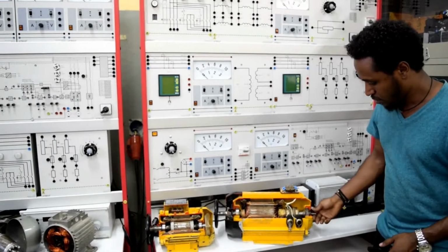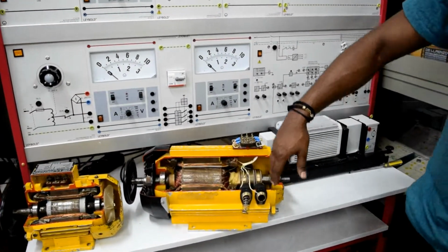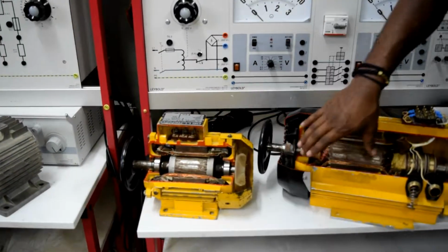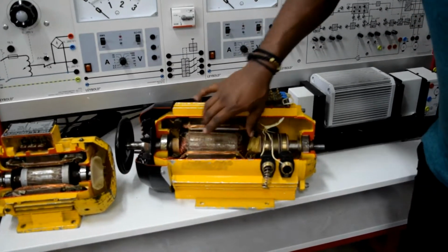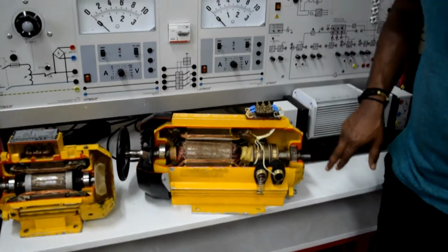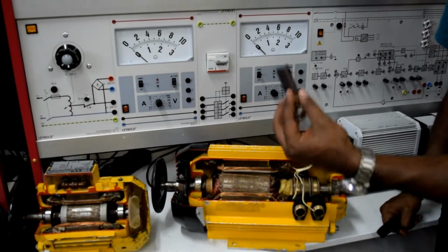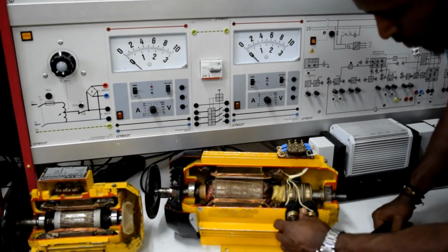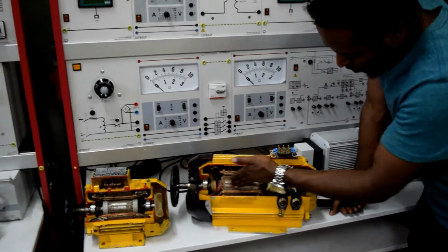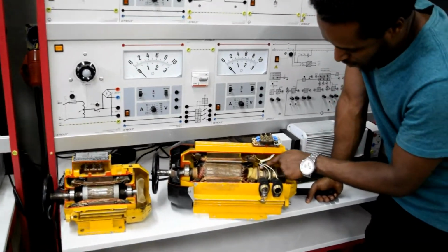So when we see the phase wound here, we have a slip ring. That means before we saw that the squirrel cage is short circuited on both sides, but when we come to phase wound, the other side of the rotor is connected to the slip rings. So here the slip rings are connected with the brush so that they can take current out or into the machine. So this one is phase wound type, but the other parts are the same. The difference is the slip rings.